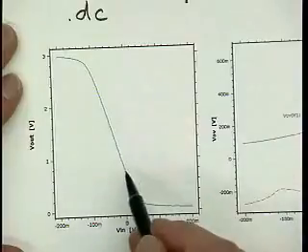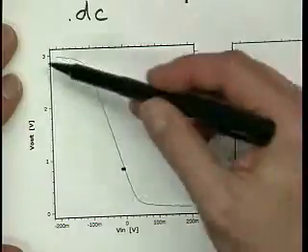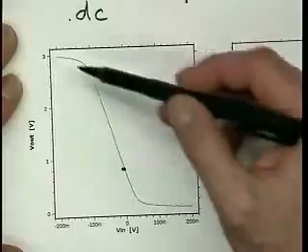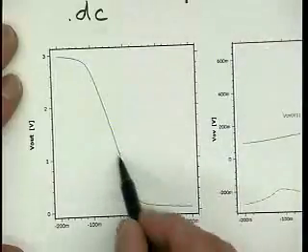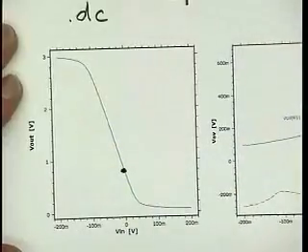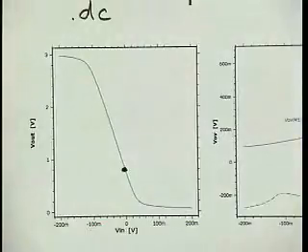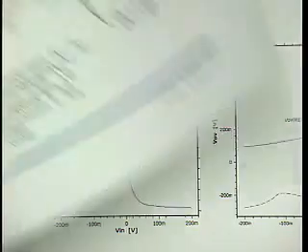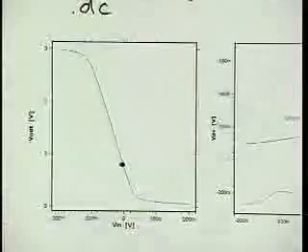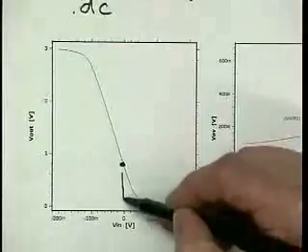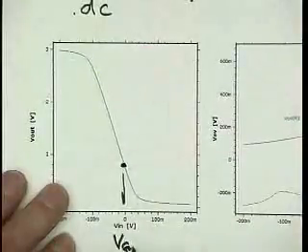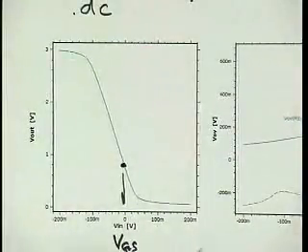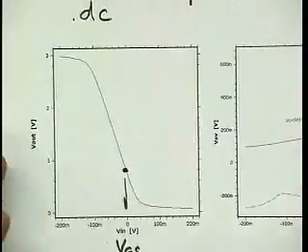So this is the characteristic. Not too surprising. This is an inverting stage, and it's inverting about a bias point of 0 volts. Right? I do everything with respect to the nominal VGS that comes out of this stage. So that's why I call this 0 volts. This is really the VGS that I need to run that current that my other circuit calculates.